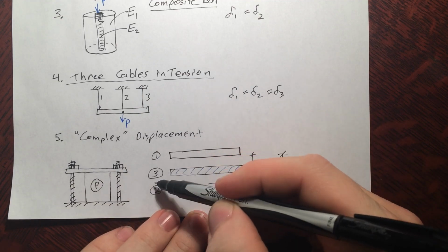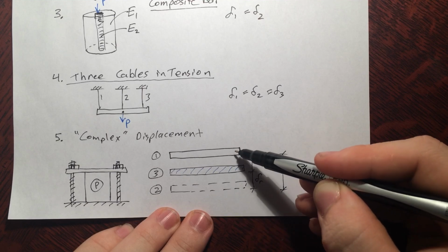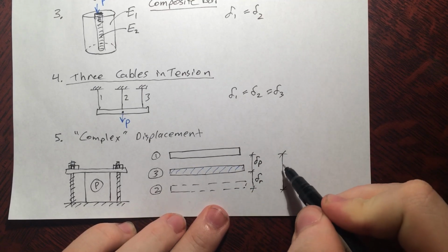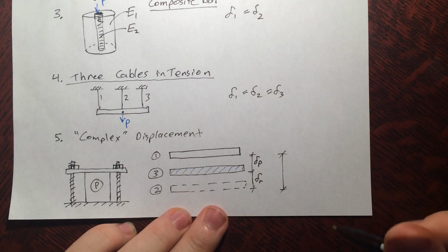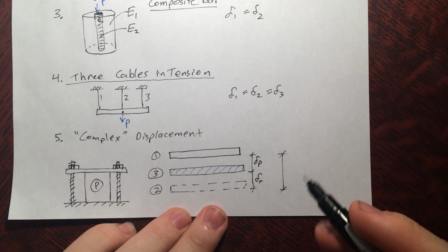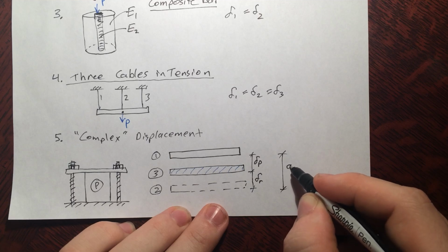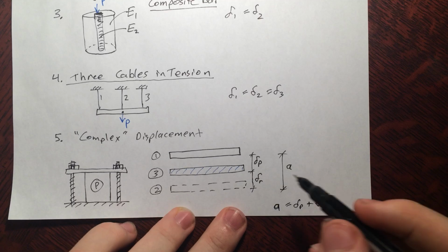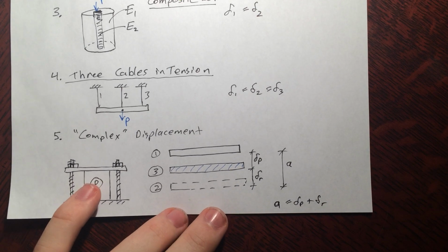Now I said it's 3 steps, so the plastic initially gets compressed down to here, then it goes up to here, so its final resting place is here. That means from the initial position to its final resting position, the plastic has moved a displacement this much. And then this overall bit here is the amount by which I screwed the nuts down on the top. It's probably going to give you some sort of pitch and a number of turns, where they'll say you move it 5 millimeters down. Anyway, you're going to know a number here. I'll give it a variable A. And then very simply we can say A equals 2 delta plastic plus delta of the rods. And then you do the same thing, you put NL over AE in there, and then you solve with your equilibrium equations.